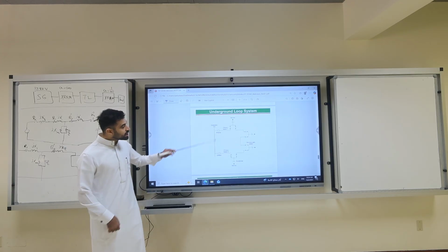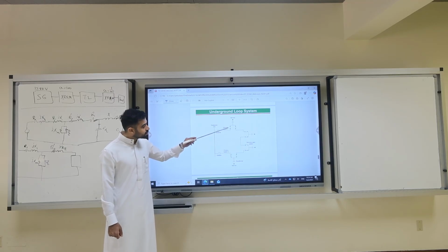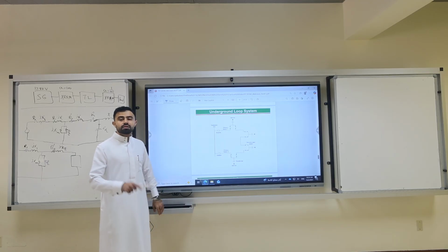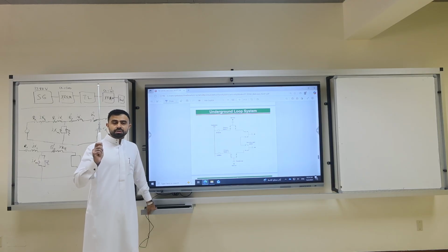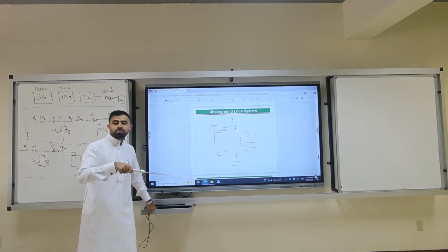The underground here, the difference is we don't have recloser. We have what? Switches. Why? Because of the recloser. I told you how it works. There is a fault, close. Wait a few cycles, open. Close. Open. Close. Open. As long as the fault is there, it will remain open until somebody manually closes it.